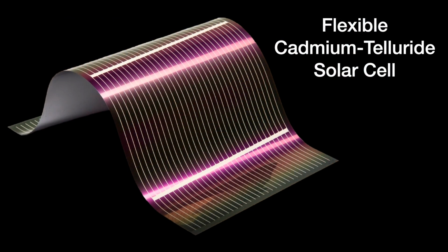Relatively low in cost, cadmium and tellurium can be compounded into cadmium telluride thin-film photovoltaic modules. Unlike silicon solar cells that use actual bulk slices of silicon, these only use a thin, vapor-deposited film, so they use much less material and are hence cheaper to manufacture. The thinness means that you can deposit the film on flexible materials like you see here. This also adds some unique manufacturing possibilities over the rigid and brittle silicon cells.